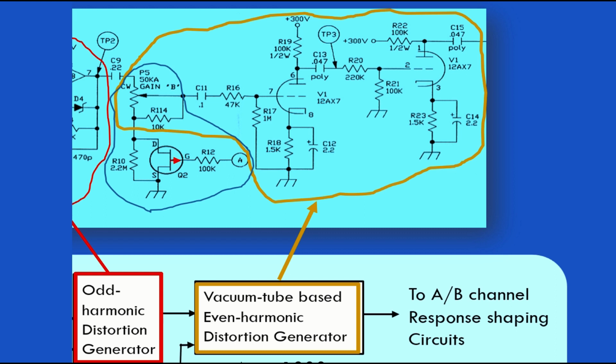And in this particular design, it's about a gain of 60. But there's an explicit voltage divider over here, which cuts that back by 1/3. So we got a gain of about 20 from pin 7 to pin 2 of this dual triode vacuum tube. And then on this side, we have a gain of about 60. How do I know that?